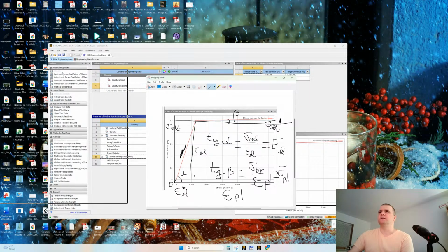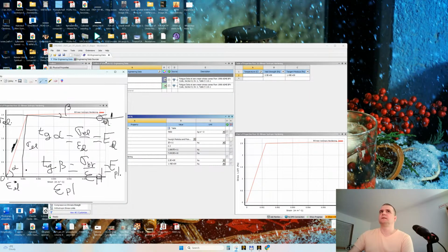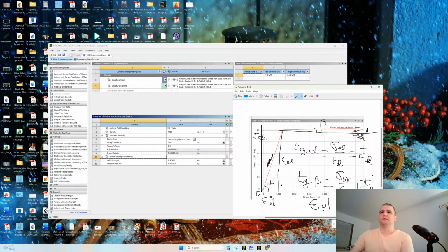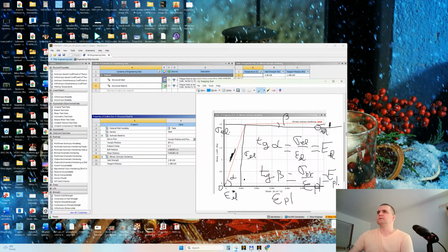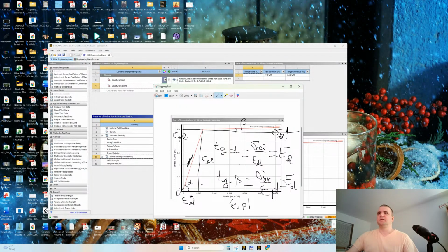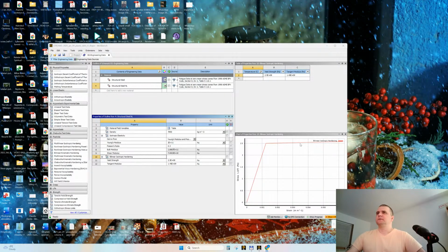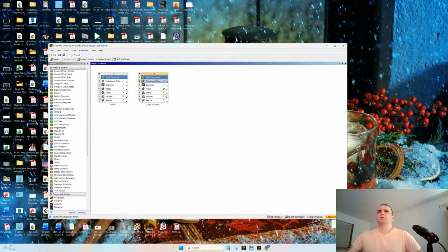This is what this value is, tangent modulus, yes? In comparison with the Young's modulus. Young modulus is the tangent alpha for this triangle, for the elastic portion. And the tangent modulus is the modulus for the plastic portion. You can find broader explanations on Google, but these describe the plastic domain. All right, where were we? Here, double click.